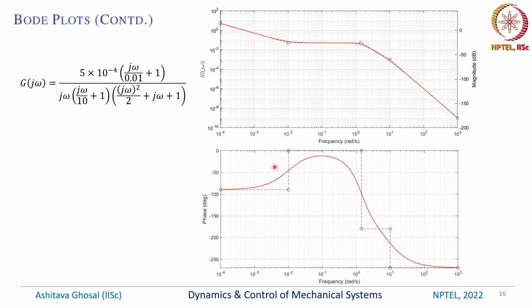The magnitude and phase plots can be done very easily. Remember, it is log magnitude, so it is made of pieces, and we need to plot each piece and then smoothly connect each piece.